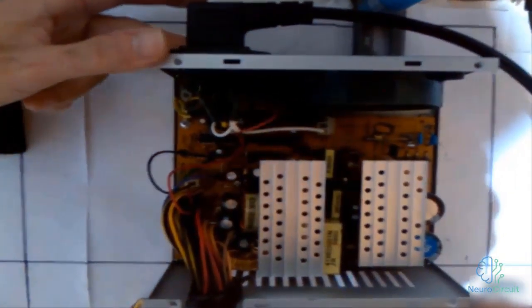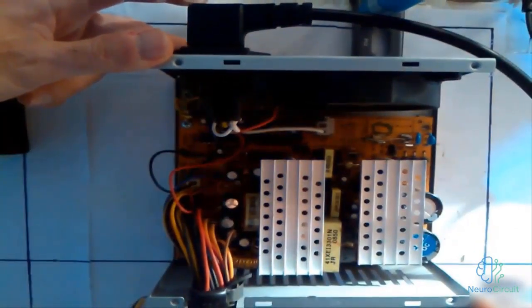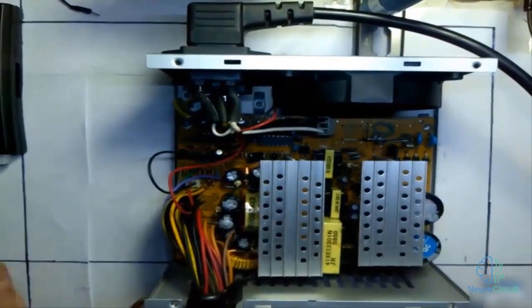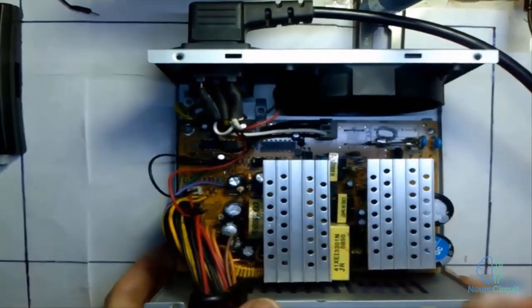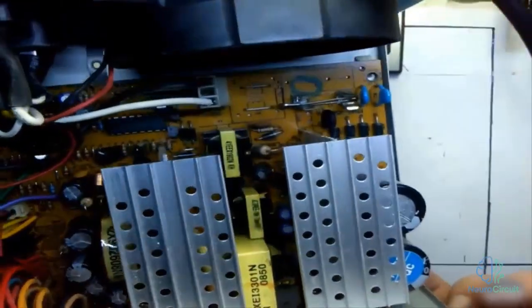I'm turning the power supply on. You can see that the test lamp's light is clearly visible here. This means the power supply has a complete short circuit. That's exactly why you're told to always use a test lamp. This power supply actually has a damaged primary circuit, and if I bring the power supply a bit closer, you can even see the burn marks.